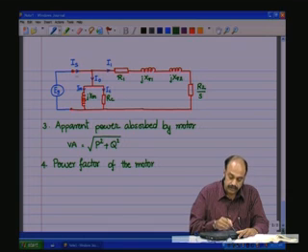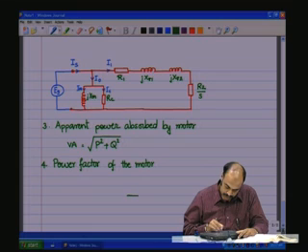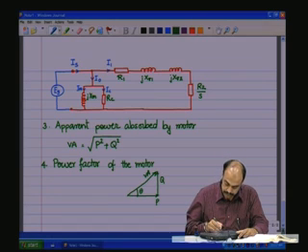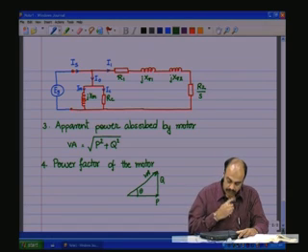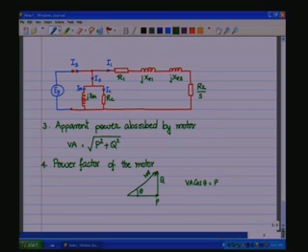Now we have the active and the reactive power, and therefore we know that this is the active power, orthogonal is the reactive power, and then this is the VA. This is the power factor angle. So VA cos theta should be equal to P. So power factor PF is equal to cos theta is equal to P by VA.